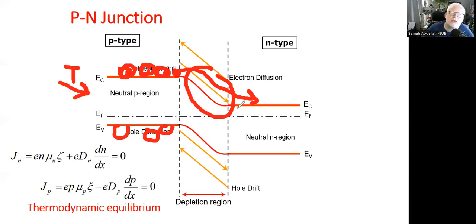And this is basically one of the concepts we can use to understand how you can turn temperature variation into electrical signal variation, or into electrons and holes. So now you can see from this example how temperature is turned into current and voltage. And this is a basic concept on the effect of exposing a p-n junction to temperature, where the p-n junction uses the built-in potential to drift the generated carriers and convert them into electrical current. So this is a valid example.